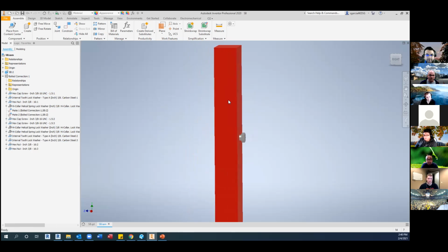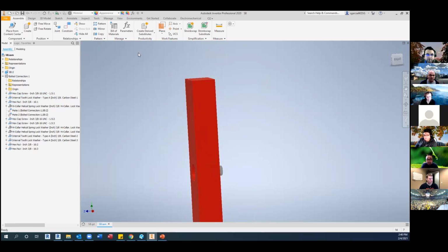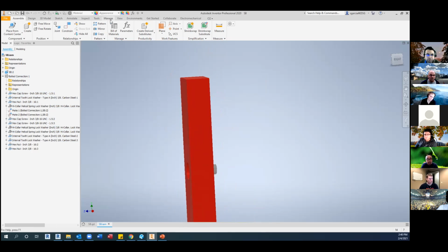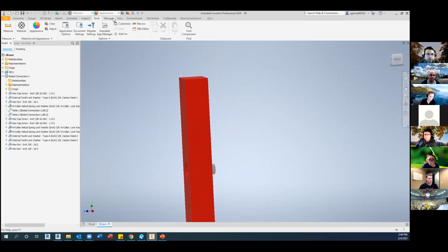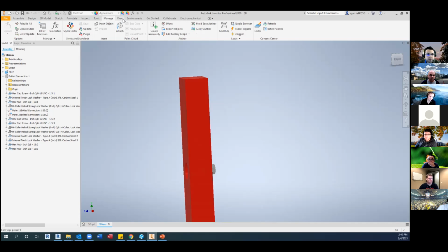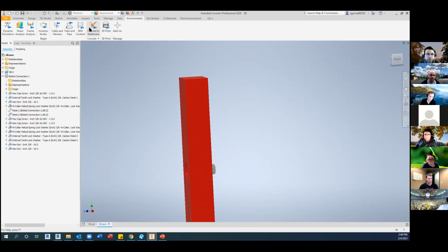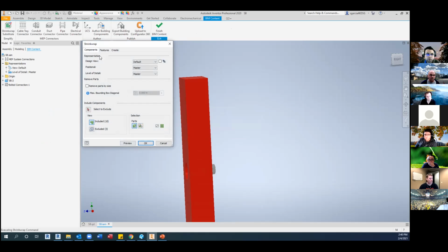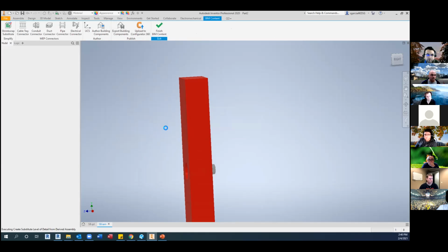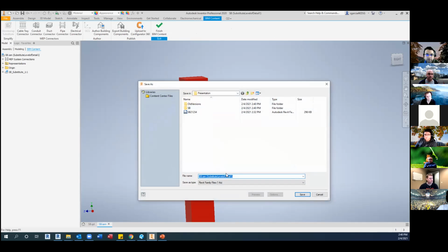So now that I have my assembly on Inventor, again, I can repeat the same process. I can move to export part as a Revit family. Okay, so beam content, if I export building components, it's going to ask me to shrink wrap this part because it's kind of heavy, but it's still going to work. It's going to ask me again, I'm saving as a Revit family.